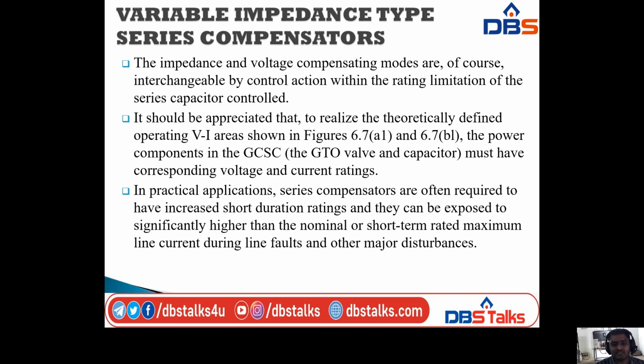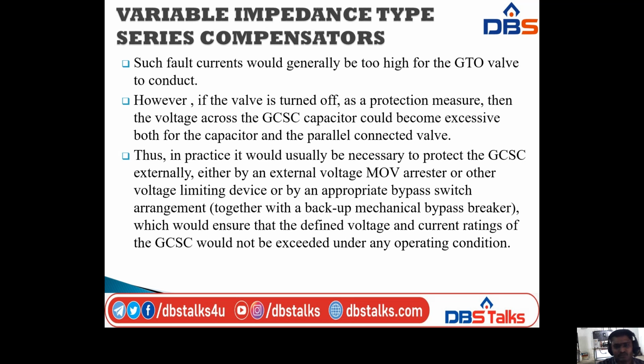In practical applications, series compensators are often required to have increased short duration ratings, and they can be exposed to significantly higher than the normal or short-term rated maximum line current during line faults and other major disturbances. Such fault currents would generally be too high for the GTO valve to conduct.